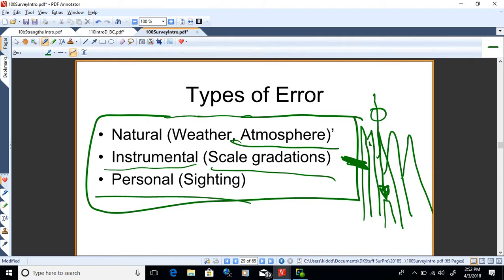Now, if the wind isn't blowing too bad, what do you suppose you do to get the best results you can get? Where would you sight if this string is swaying? Top, actually the lower the better on a string like that. Well, okay, I think kind of the idea of what you're getting at would be the middle of the swing, right? Where you assume that person's trying to hold that plumb bob on the point, and as that plumb bob sways a little bit, you hope that on average, that's when they're over the point.